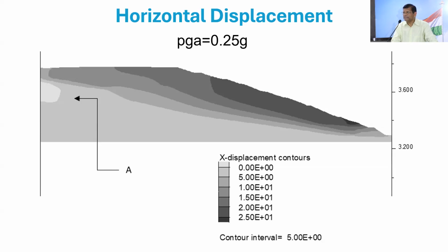The guideline which comes from hydro dams and other important structures, we normally see, is that we want to stay within 1 foot, acceptable. But again, it is not a standard, it all depends on your area. But this model is clearly saying that if it has gone 25 feet, this has liquefied. So seismic liquefaction is possible.